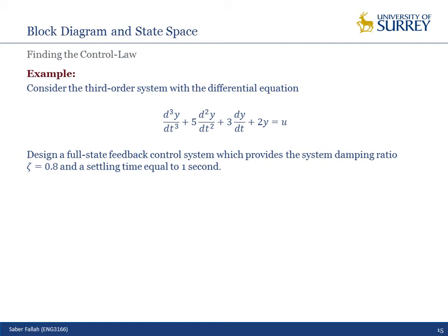Look, we have the characteristic equation, as I said. The characteristic equation for the uncontrolled system is the determinant of sI minus F, and for the control system, it is the determinant of sI minus (F minus JK). We need to compare these two characteristic equations, and using this, I need to calculate K such that I get the correct response. So I will explain here.